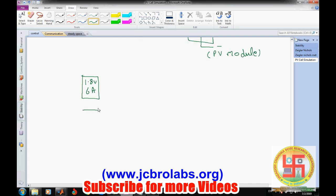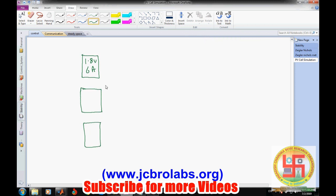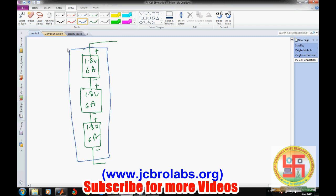So we can have these three different modules in series, and each one is having 1.8 volt 6 amp, and all these are connected in series. Now this total combination will generate 5.4 volt as open circuit voltage, and the short circuit current will remain the same.